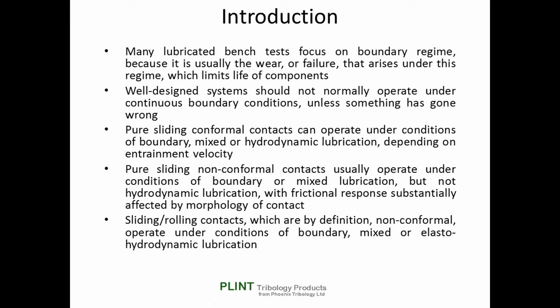Pure sliding conformal contacts can operate under conditions of boundary, mixed or hydrodynamic lubrication, depending on the entrainment velocity. Pure sliding non-conformal contacts usually operate under conditions of boundary or mixed lubrication, but not hydrodynamic lubrication, with frictional response substantially affected by the morphology of the contact. Sliding rolling contacts, which are by definition non-conformal, operate under conditions of boundary, mixed or elasto-hydrodynamic lubrication.